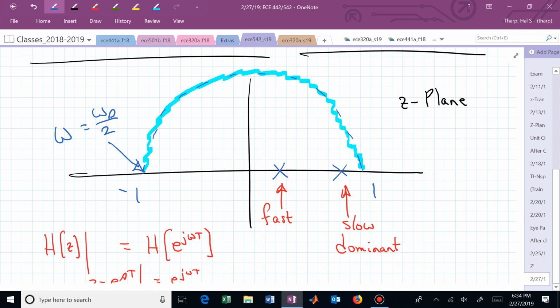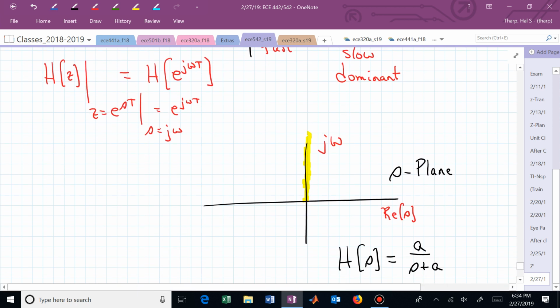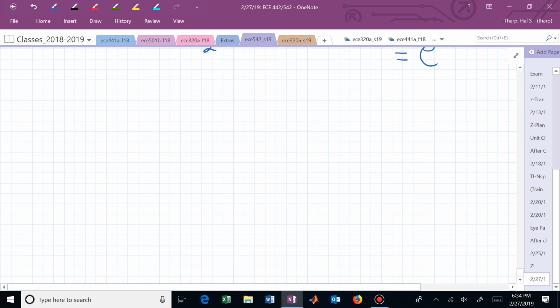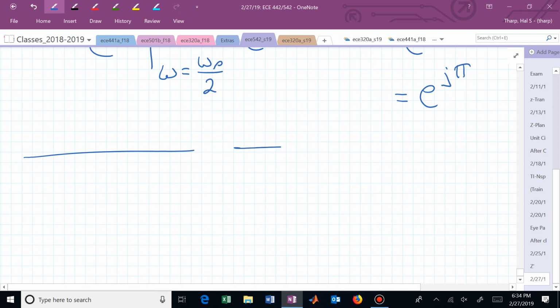The highest frequency we can really see is omega sub s over 2, and that's where this Nyquist, you could think of, is coming from. The Nyquist frequency is half your sampling frequency. How fast do we typically sample in this class? 30 times. So we're sampling much faster than the extreme frequency that we can see. That's now our discrete equivalent without a preceding hold device using numerical integration approaches.